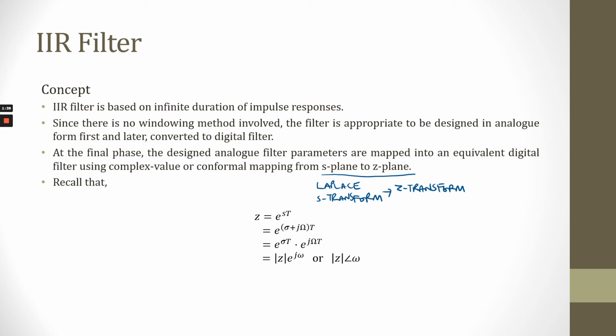The second approach to designing IIR digital filters is to use an algorithmic design procedure, which generally requires the use of a computer to solve a set of linear and nonlinear equations. These methods may be used to design digital filters with arbitrary frequency response characteristics for which no analog filter prototype exists, or to design filters when other types of constraints are imposed on the design.